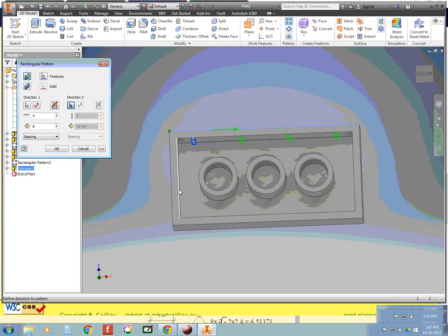And I think if I choose this inside, yeah, this will probably work better. Flip the direction. Make sure you choose the inside. And now let's see. That distance inside is going to be 15.8 minus 2.4. So let's start with that 15.8. Let's go minus the 1.2 wall thickness, whoops, might help if I put that minus in there, minus 1.2 for one wall thickness, minus 1.2 for the other wall thickness.